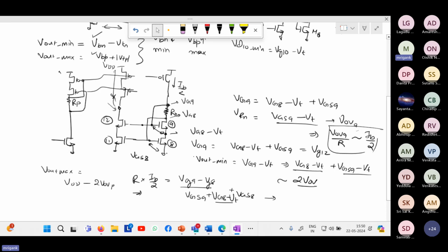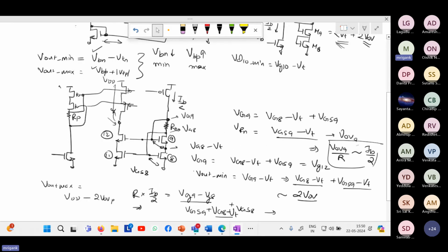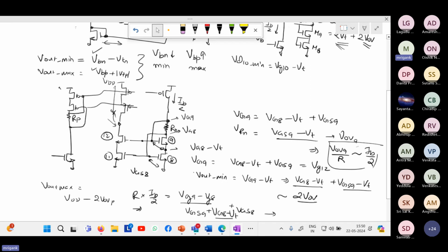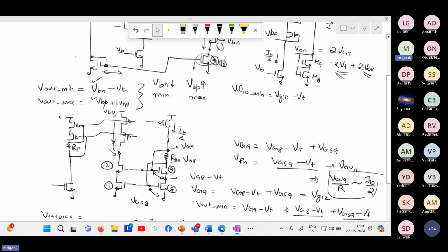So this is more common because otherwise your voltage swing will be poorer at the output. The first mechanism that we have seen, there you are having VT plus 2V overdrive as the gate voltage VBN, which definitely leads to poorer swing at the output. So if you want to improve your swing, you can test with this particular scheme, and you will see that if you're working in, say, a voltage follower configuration, the range for which it works will be extended.